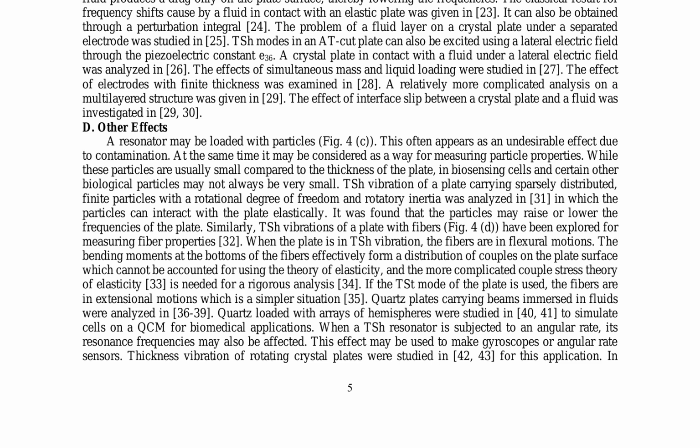A detailed examination of the effects of fluids, particles, and fibers on the resonant frequencies reveals the importance of considering these factors in specific applications. For instance, the viscoelastic properties of fluids and the mechanical properties of particles and fibers significantly impact the resonant frequencies. The shear modulus of the mass layer and the bonding conditions between the mass layer and the plate also play critical roles. By understanding these complex interactions, researchers can optimize the design of crystal plate-based sensors and devices for various